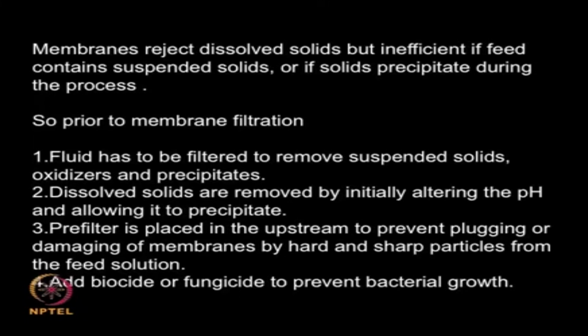So membranes reject dissolved solids, but then they are very inefficient if the feed contains suspended solids. So it is not very good to have suspended solids if you want to resort to membrane, or if the solids start precipitating out during the membrane process. When do solids precipitate out? It can precipitate out if there is going to be a change in pH, or if there is going to be a colloid and agglomeration formation. So prior to the membrane filtration we need to have a lot of pre-processing.